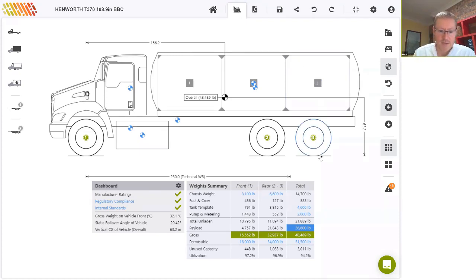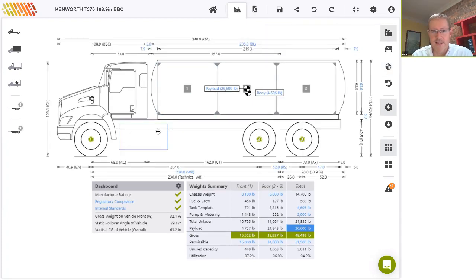Then one last point, or question as well. It's just a comment that you've located the pump where the fuel tank would typically be positioned. So I suppose you could move the pump back slightly on the chassis. And that's, again, something that you normally need to check with the chassis manufacturer or your dealer in terms of the layout of the fuel tank position, the battery box, the DEF tank, the exhaust, and figure out exactly where you have available chassis space to fit any additional equipment. So that's a good point.